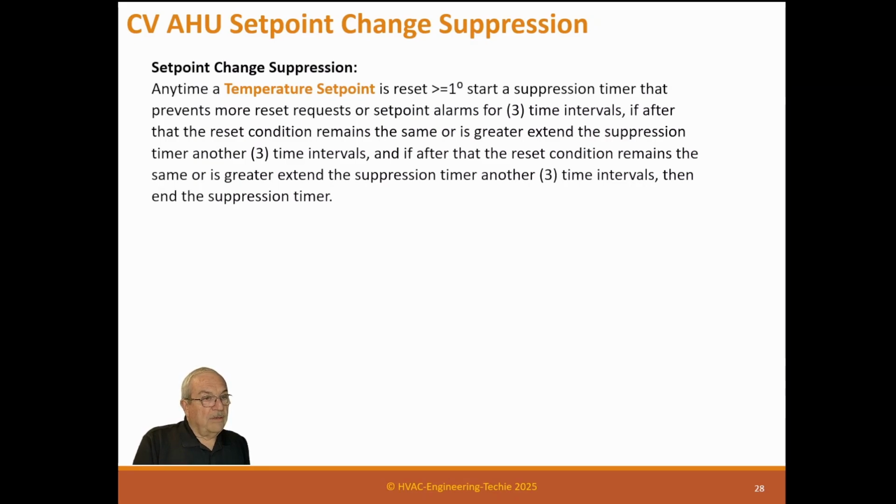Well, we don't want that. We'd like it to be suppressed for at least 30 minutes, somewhere around there. It could be less, but right around that time period. So we give it time to react, because it could be that the room has a lot of mass and it takes the air some time to change the temperature in the room. So we want to give it a chance. We're going to give it this 30-minute time period before we let it go back to alarm and do set requests. This will slow down us driving the reset all the way up or all the way down. So what we're trying to do is not let that happen.